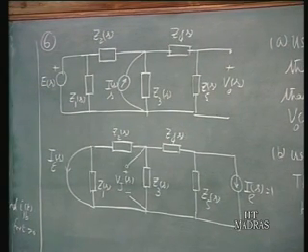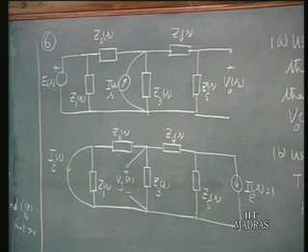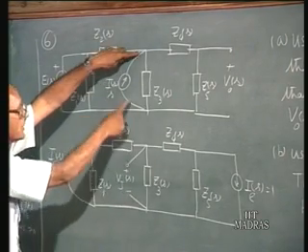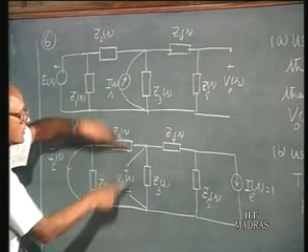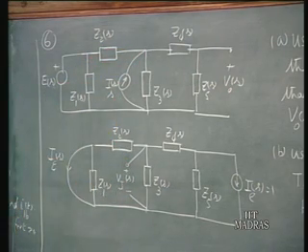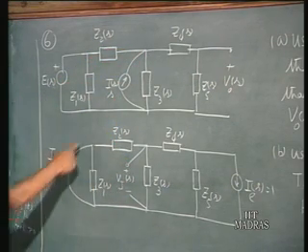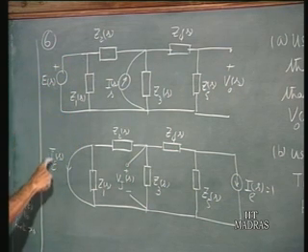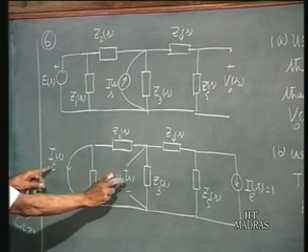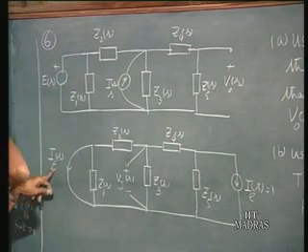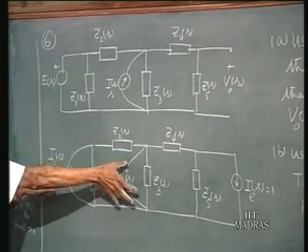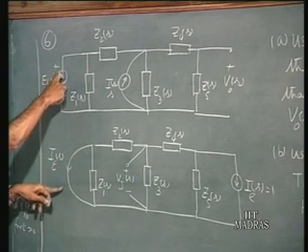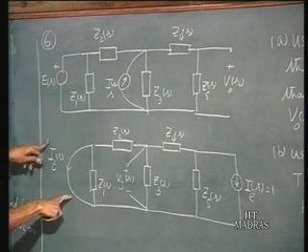So if you use that current source and measure this voltage Vj of S here, that is where our current source was present earlier, you measure this voltage Vj of S, and calculate the current. Because this voltage source is replaced by a short circuit, calculate IE of S. So you calculate Vj of S, the open circuit voltage across the terminals of the old current source, and the short circuit current through the old voltage source location.